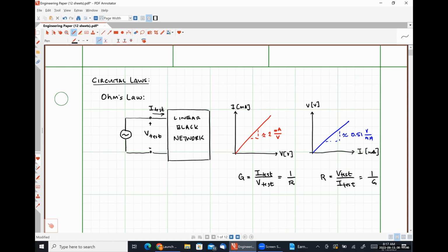In practice, resistance is used as a quantity a whole heck of a lot more than conductance is. You don't really start seeing conductance measurements until you get into things like transmission line theory, where the conductance is used to represent current leakage between your conductors in a transmission line system. So for the overwhelming majority of this class, effectively every day after today, anytime you see a conductance, you should just take the reciprocal of it to turn it into a resistance, and then use all of the resistance techniques that we're going to develop in this class to deal with it.